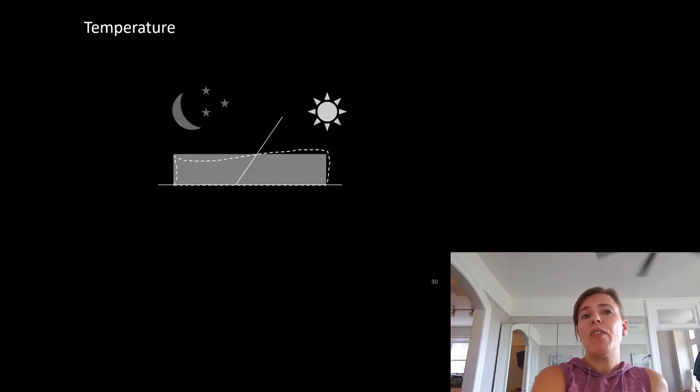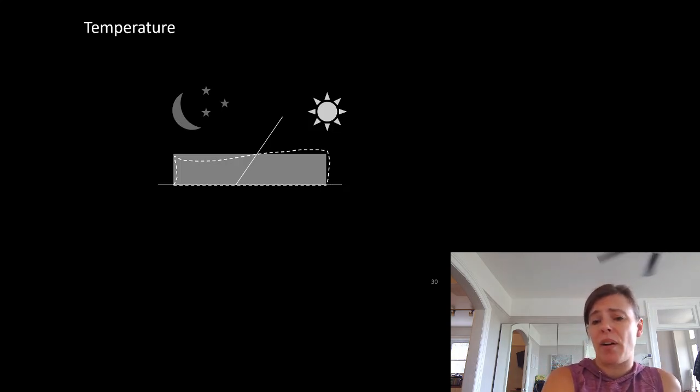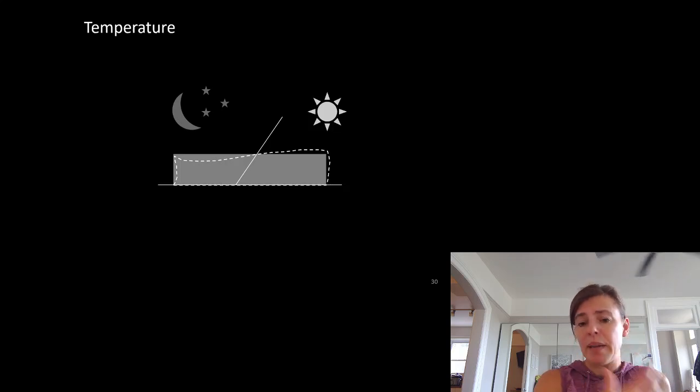Temperature. If we have one side of our building heating up in the sun, and the other side is cold, we can see contraction on one side and expansion on another. We can see big scale movements. If our building's enclosed, it doesn't really tend to matter. We're usually governed with an internal climate. So we might see 15 degrees to 30 degrees inside a building. It tends to be governed pretty tightly.